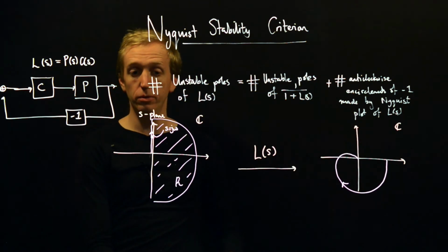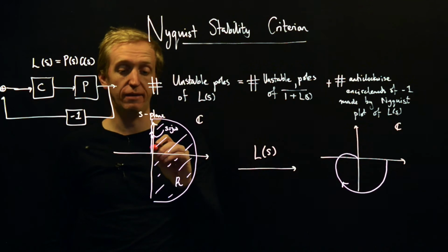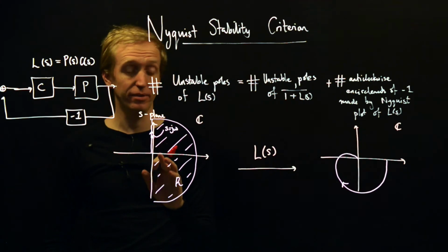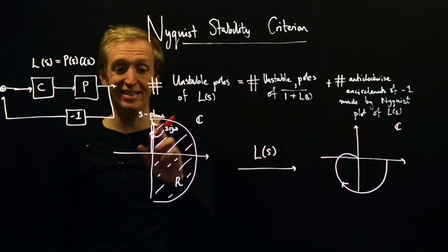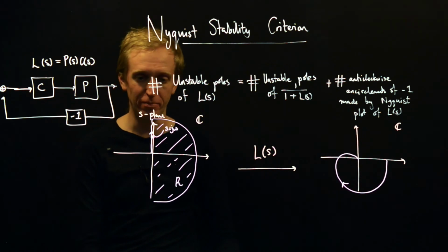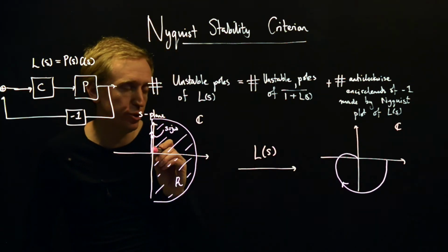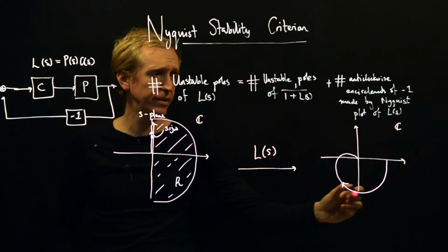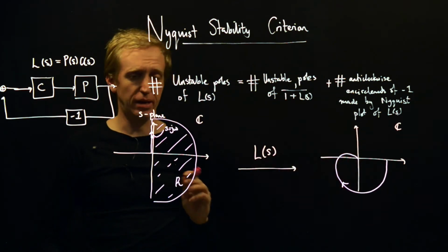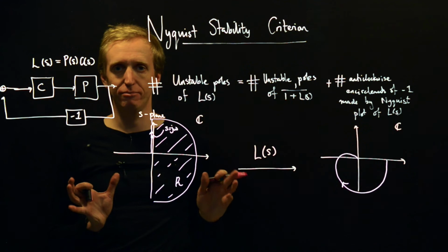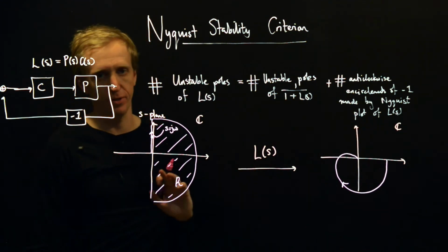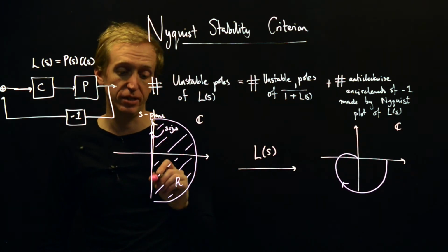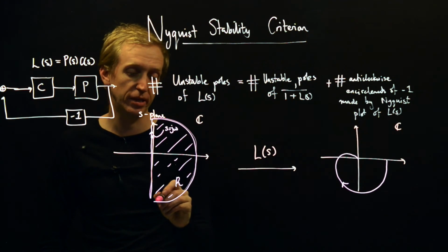So we know that to apply our argument principle, we have to take a closed contour going around our region R, and ideally that contour should be in the anti-clockwise direction. And we already see another irritating thing: when producing our Nyquist plot, our contour went that way, resulting in an arrow going like that. And we don't want to change the direction of Nyquist plots. So we're just going to have to take care of that, but we'll get onto that in a second. The other thing we have to do is turn this into a closed contour. So we have to close things off.